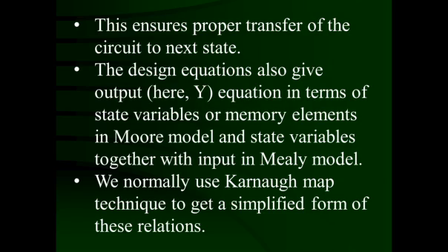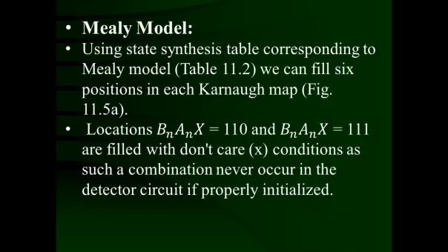So here there is a difference, remember: output Y is a function of the present value of the output only of flip-flops A and B. That means Y is a function of An and Bn only in case of the Moore model, but in the Mealy model it is a function of the present output, that is An and Bn, as well as the input, that is it is also a function of X. So that way we have to draw the Karnaugh map for the output here.